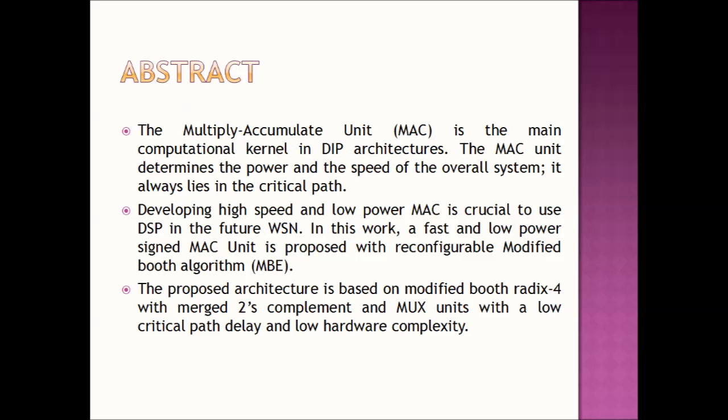If you look at our project, as I said earlier, the MAC unit is such an important architectural block present in processors which are used in DSP applications. Since a lot of arithmetic calculation happens here, a MAC unit is often a determiner of the processor speed and the power consumption too. Since it always lies in the critical path, optimizing the MAC unit ensures most of the delays and other drawbacks of the processors are removed.